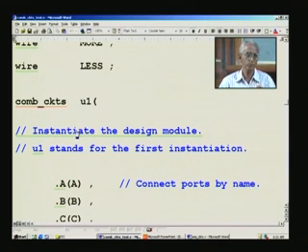So, it is similar to, suppose you have a circuit diagram, let us say we have TTL gates, say 74LS00 you have used, there are 10 numbers on a board, and how do you identify? You identify them as U1, U2, U3 and so on, that is the nomenclature you adopt, and the very same thing has been adopted here also.